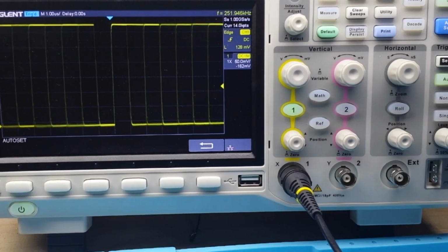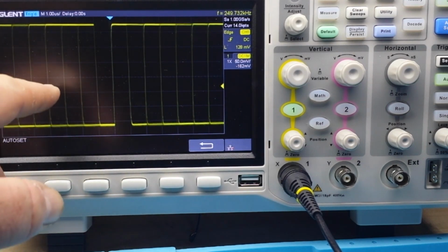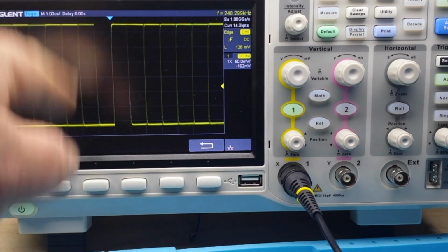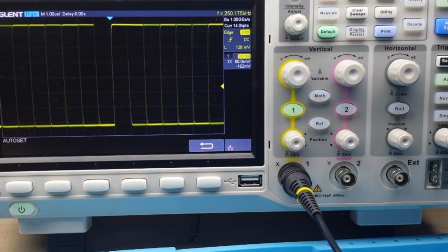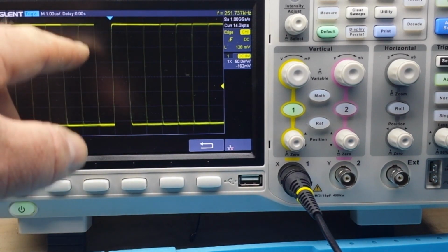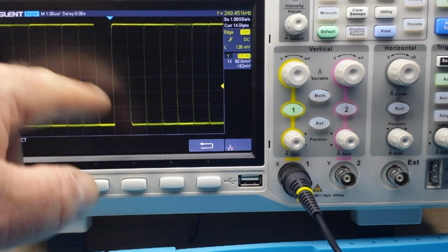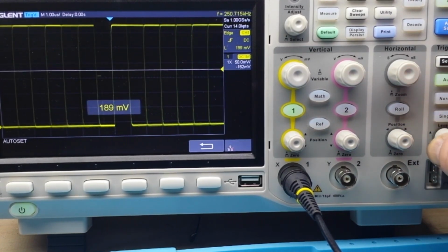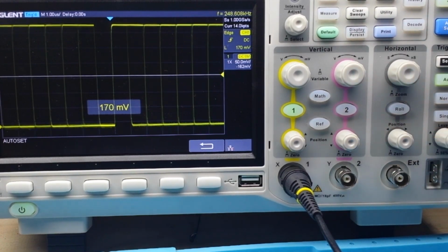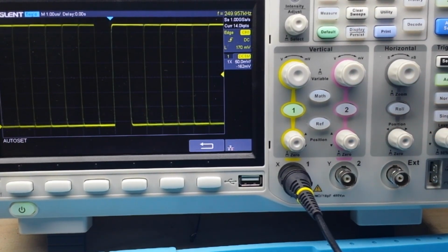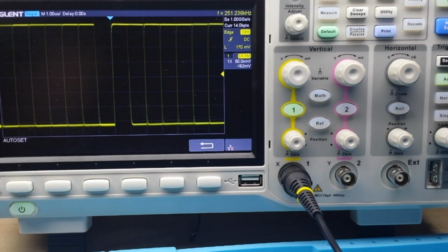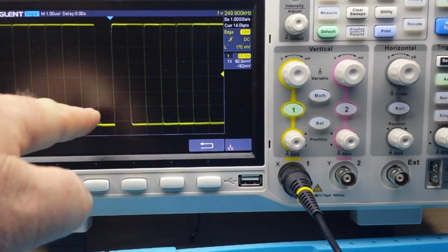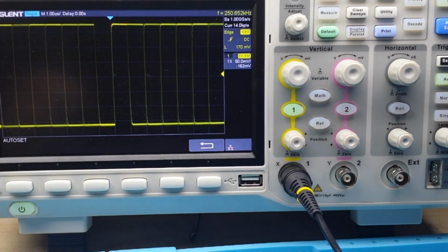Okay guys, in this case we're going to look for what's known as a runt pulse, and if you look closely in there you can kind of see them. Now you see what we got here is a square wave, and it's really hard to see, but every once in a while you see it popping. And no matter what I do with an edge trigger, we just can't key on those runt pulses. A runt pulse is a glitch where it doesn't cover the same voltage range as the rest of the signal. It can be a positive going runt or a negative going runt.